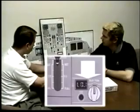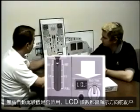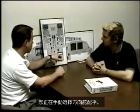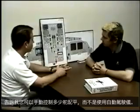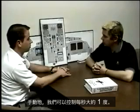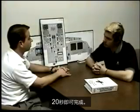Rudder trim. The LCD readout will display rudder trim, whether the autopilot's engaged or you're manually selecting rudder trim. Tell me how much rudder trim you can command manually versus the autopilot. Manually, we can command about 1 degree per second. In the A320, we get 20 degrees, so it takes approximately 20 seconds to get that.